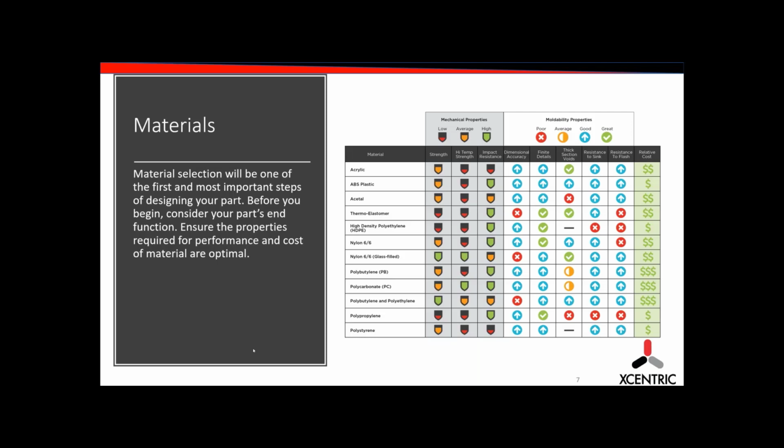And from the part geometry side, if you have a part that is prone to a high shrink just due to the design, you're going to want to select a material that can handle that design, maintain your geometry, and not vary from your tolerances as it's molded. That's when we see a lot of challenges with part design: wrong material selection due to shrinkage or part thicknesses. So material selection is probably one of the number one things to do as you're moving into injection molding.